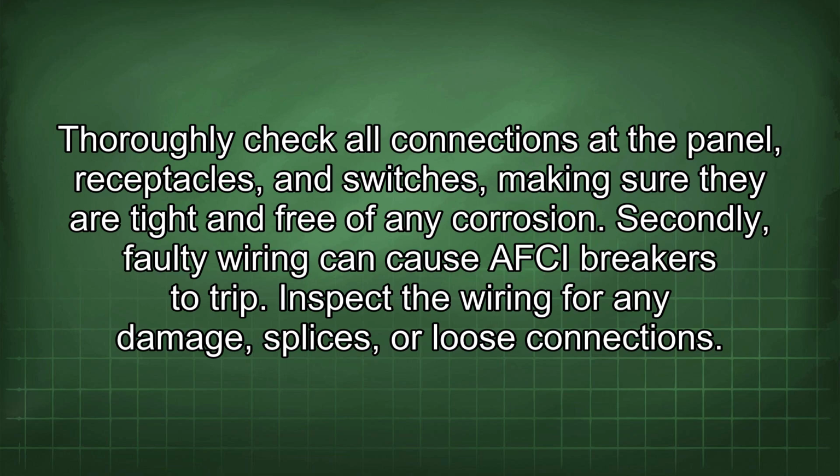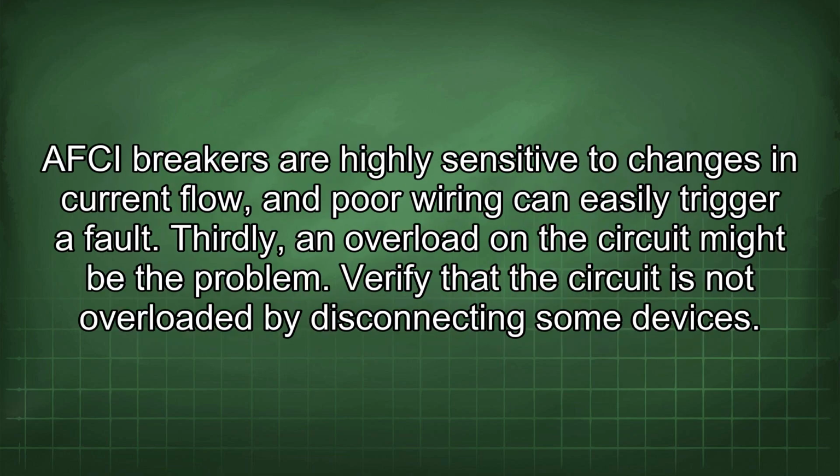Secondly, faulty wiring can cause AFCI breakers to trip. Inspect the wiring for any damage, splices, or loose connections. AFCI breakers are highly sensitive to changes in current flow, and poor wiring can easily trigger a fault.